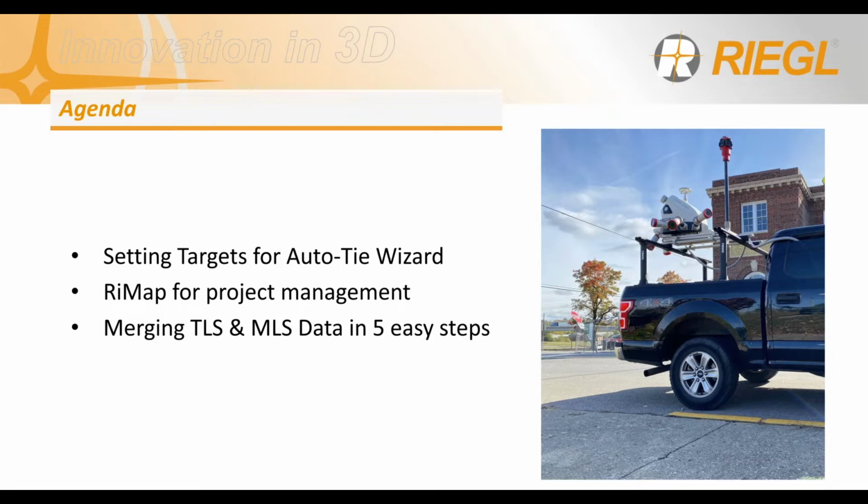If many of you do not know, in RiProcess, our LiDAR processing software, we are able to auto tie our LiDAR cloud to our control points. So today we're going to be going over best practices when actually setting the targets out in the field, and also some conditions we need to think about when we are actually out driving and doing the collect itself.